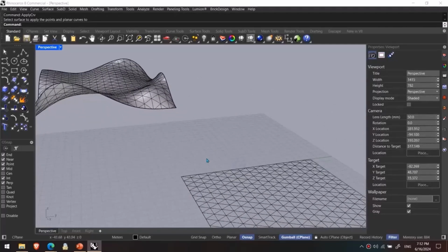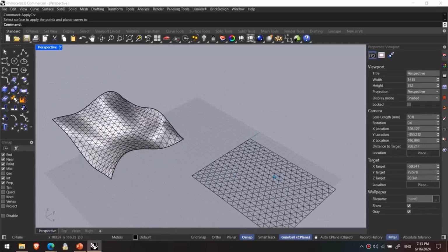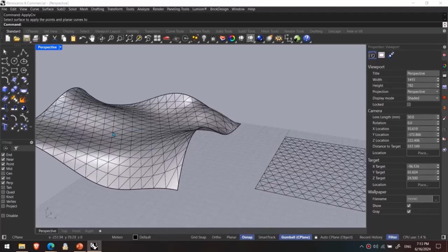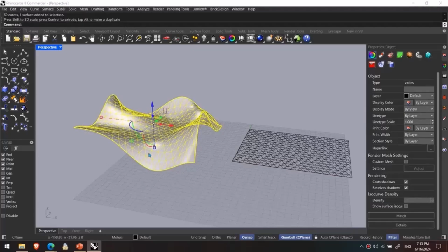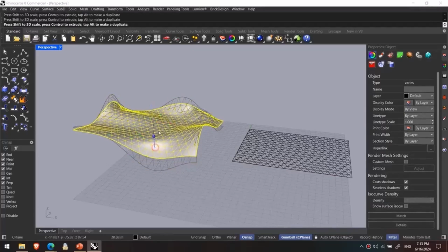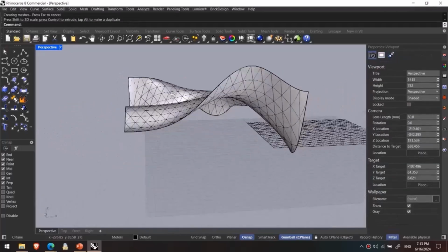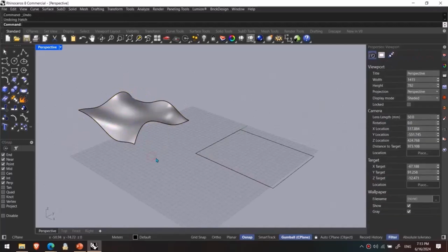Without drawing these lines or patterns, without arraying them, only by using the hatches, exploding them, and then applying them on the curves on the surface. And after transferring the curves on the surface, this is the result. And we used explode for converting the hatches to curves. And finally, I can select them and change its curveness. Look, and deform the surface like this way. Well done, Ctrl Z to undo the process.